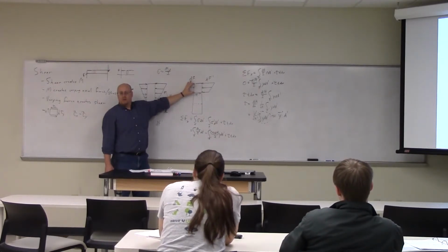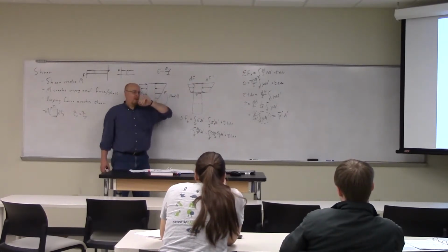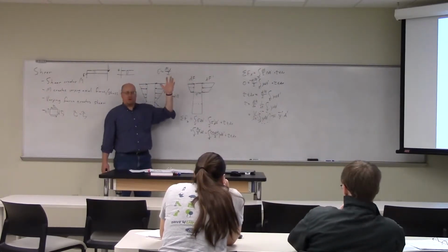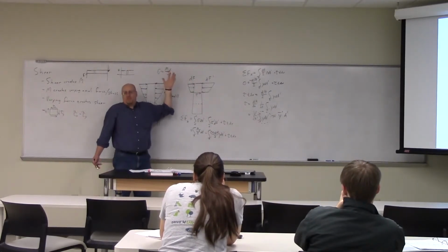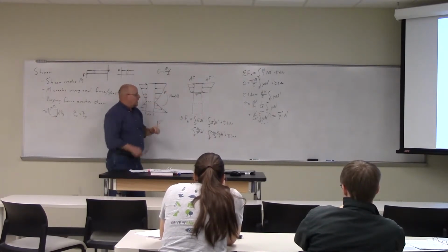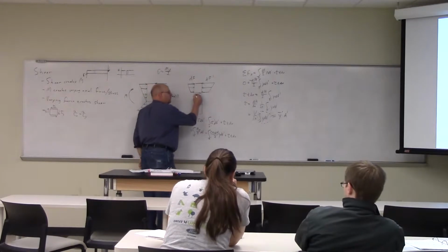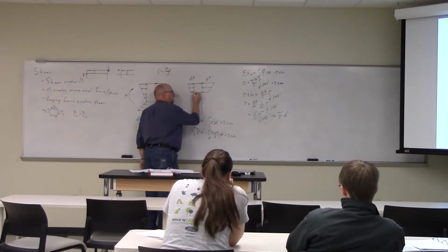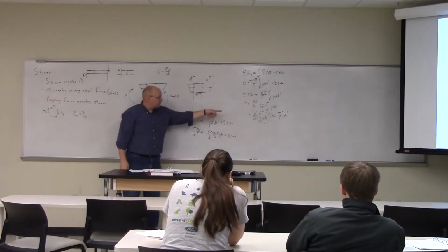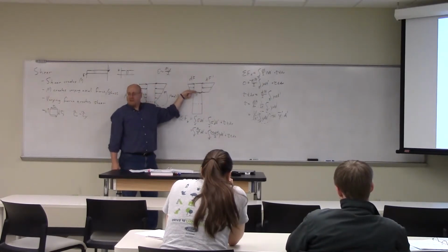Why are we limiting ourselves to the top third? I just picked a third. It's not even a third, it just looks like maybe a third. I'm just picking some random section. But the key here is we're solving for the shear stress at that interface. So the shear stress that we're solving for, this tau, is your shear stress at that particular height, y prime.